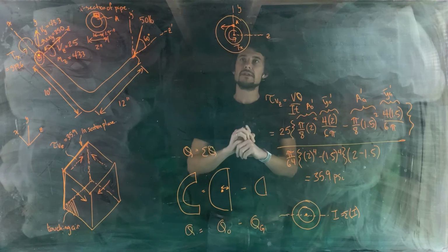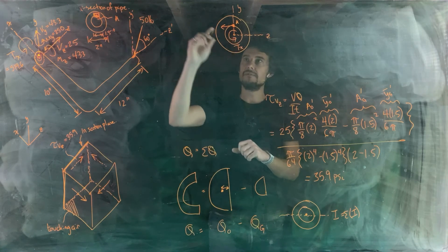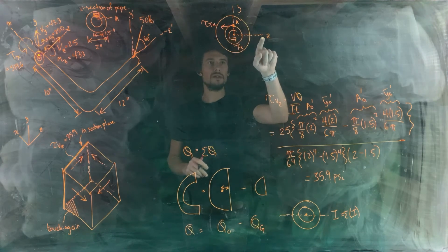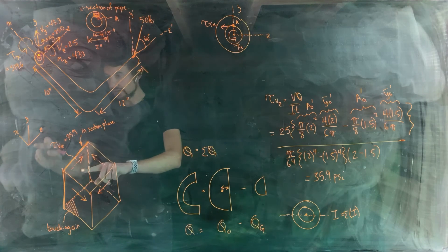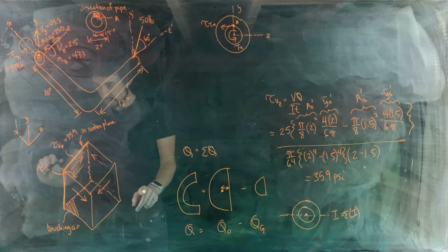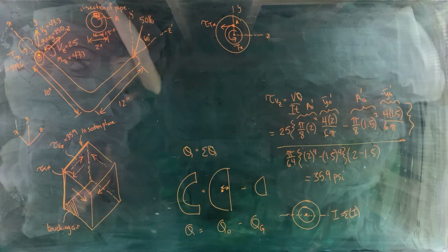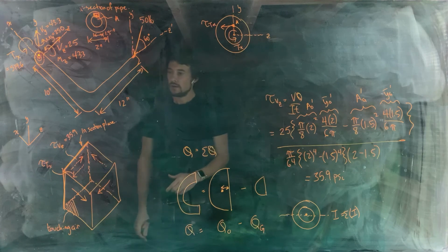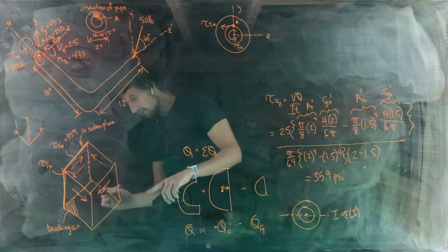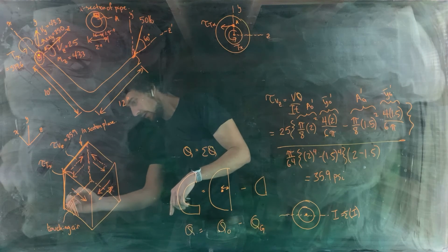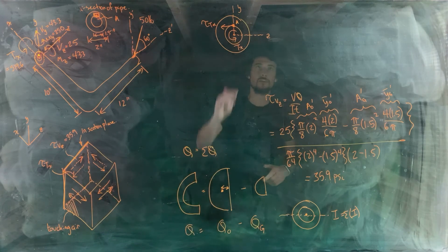Again, shear stress at point A is going to be oriented tangent to that inner circumference in this instance, and in the direction of Tx. So this is tau Tx. So that is a shear stress that's oriented in the negative z direction. So go back over here. Here's the z-axis, shear stress in the negative z direction. Okay, this is tau Tx. And then we need our other ones. So if we have shear stress like that, we need one on that surface and one down like this and another one like that.